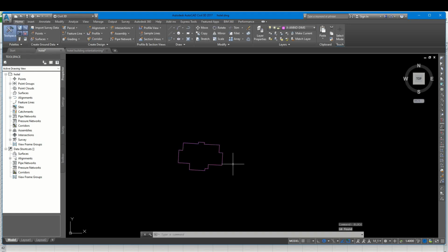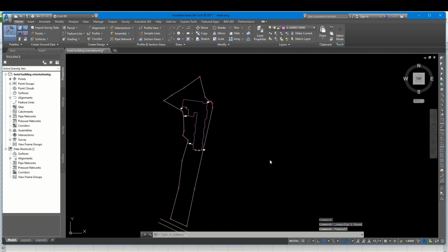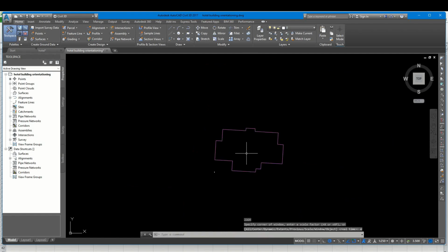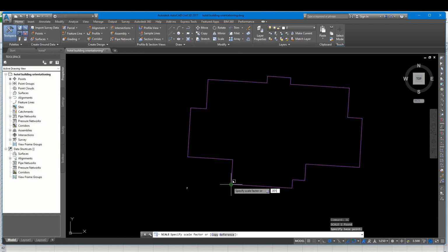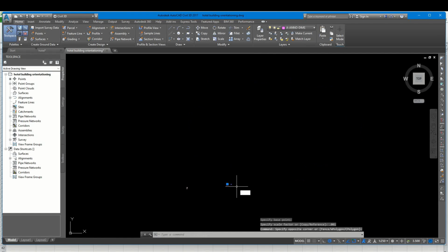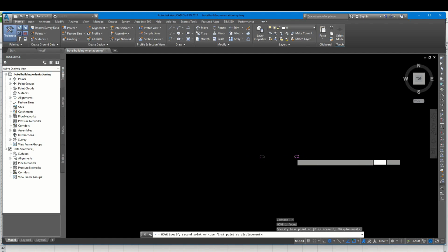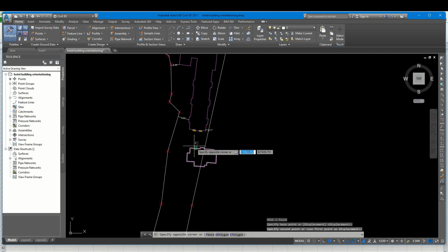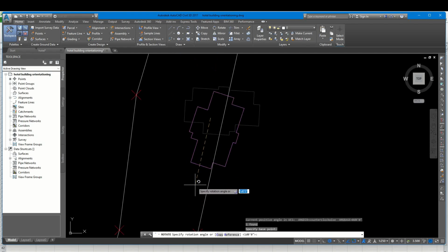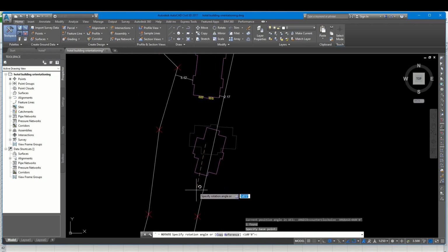So now I will do the same process by copying this to the site, paste this, Z, enter, E, enter to see this. You see, very large, so let's scale it again. 0.001. So we move the block to the original site. This will be the real life site, okay? What we have in the architecture was just the presentation. So this is the takeoff point.